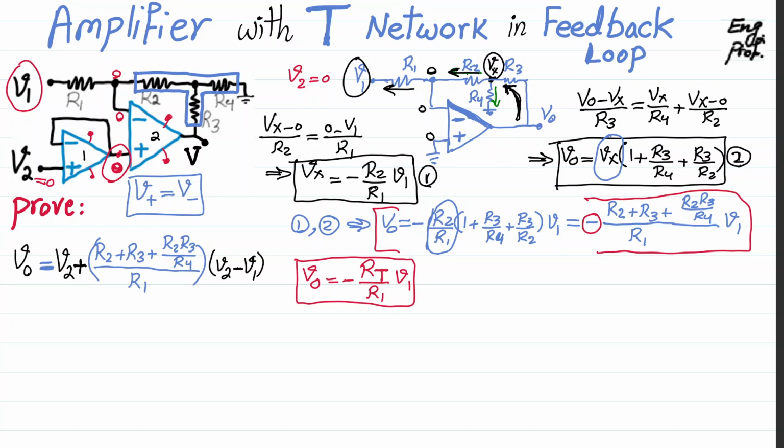What is the beauty of this? If you remember from the design of an inverting amplifier, you have a simple scheme like this: positive input terminal AC grounded, and negative input terminal connected via R1 to some V1, and some resistor RT connecting the output to the input in a feedback mode, and Vout.